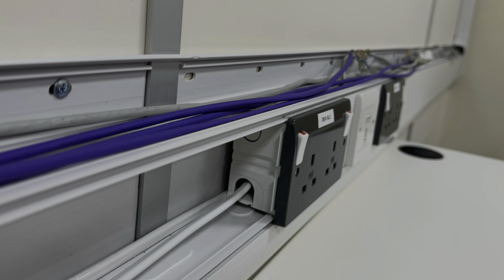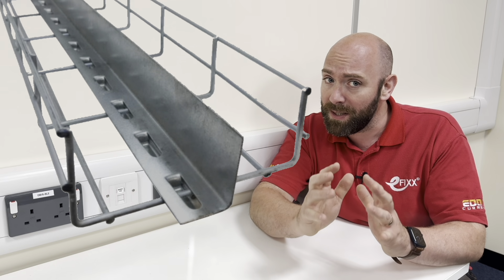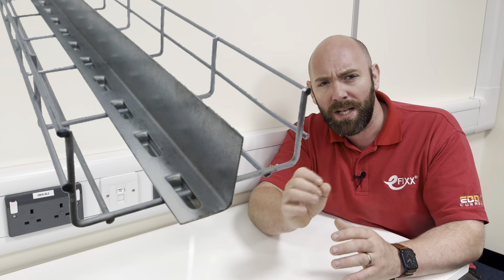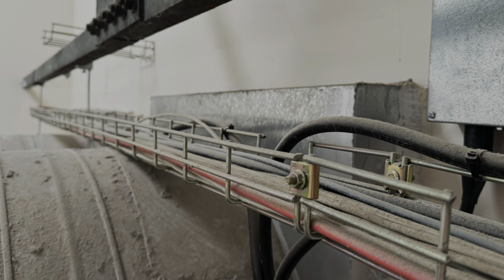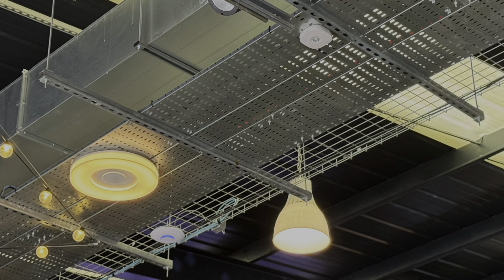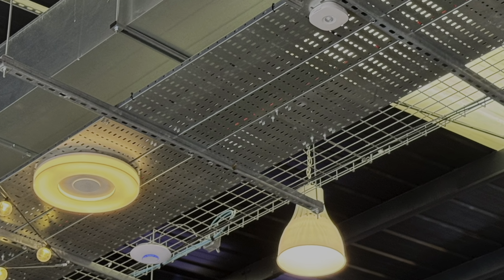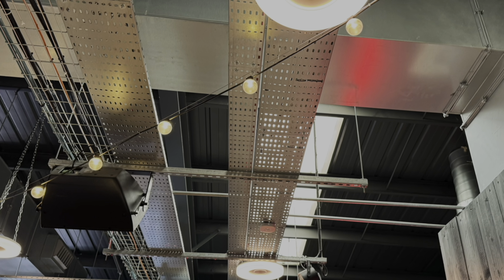We can use barriers, dividers, well, anything that will provide adequate separation. This is the same for cable tray or basket, and you tend to find on larger commercial or industrial jobs that the band 1 runs in separate containment like basket and band 2 in tray. Just a quick note though, for those who install containment for band 1 and band 2 systems, there is a regulation on the distance required between the containment.